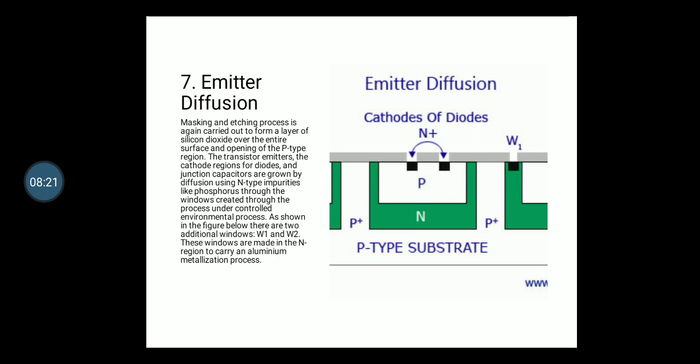The reasons for using heavily doped n regions can be explained. Aluminium, normally used for making interconnections, is a p-type impurity in silicon and can produce an unwanted rectifying contact with the lightly doped n material. However, heavy concentration of phosphorus doping causes a high degree of damage to the Si lattice, thus effectively making it semi-metallic. This n-plus layer thus makes a good ohmic contact with the aluminium layer.